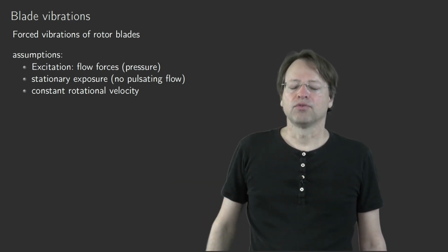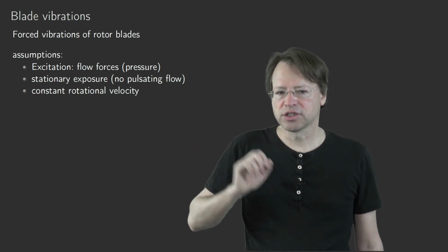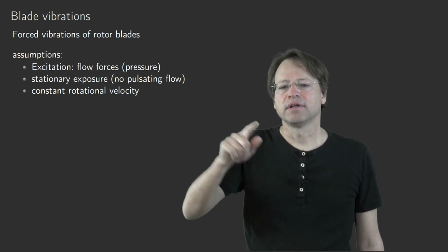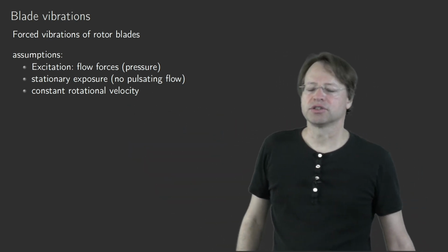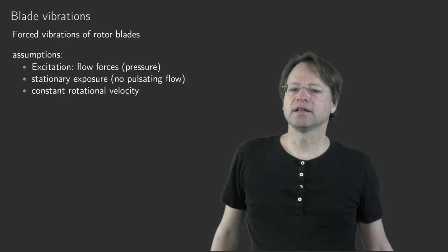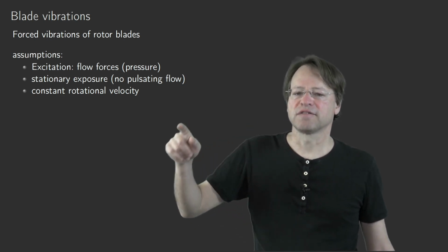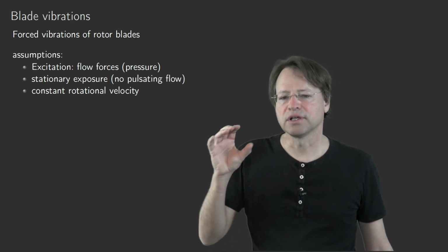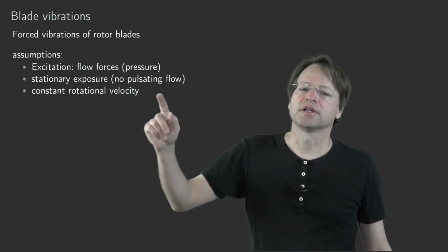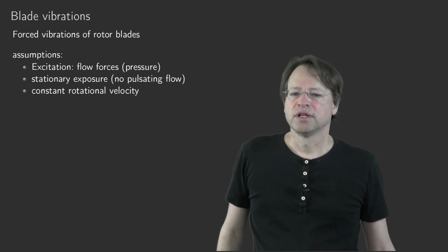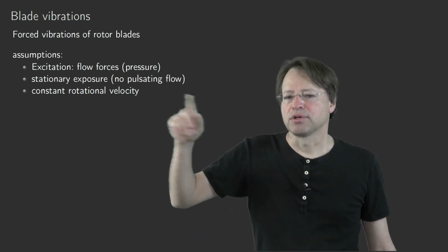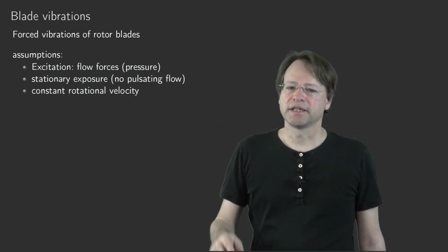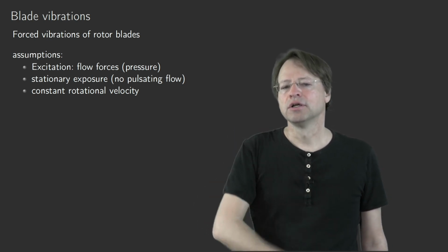So therefore, of course, the pressure changes, but it changes periodically with the rotational speed, so with the angle, and the angle repeats itself because the rotational velocity is constant, so that we have a periodic exposure of the blade to that pressure field, which leads to a periodic force that acts on the surface of the blade.